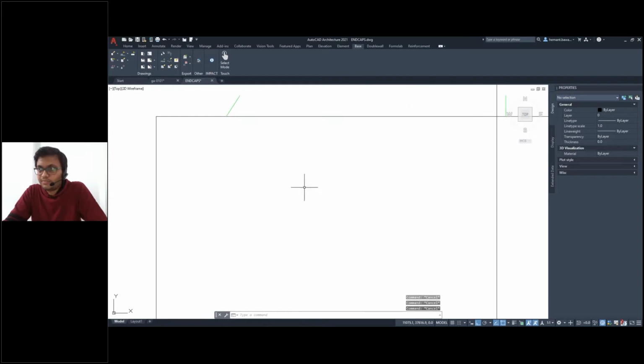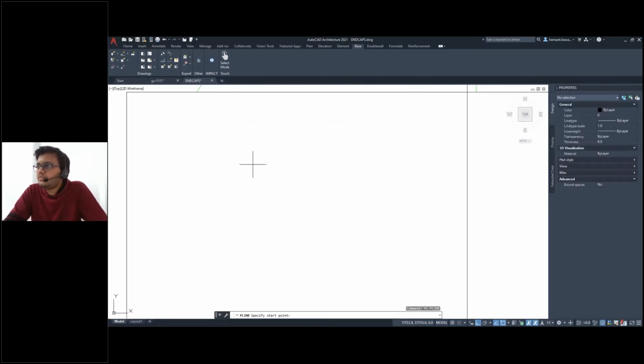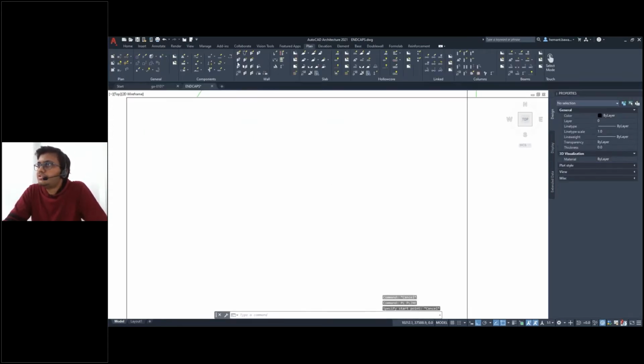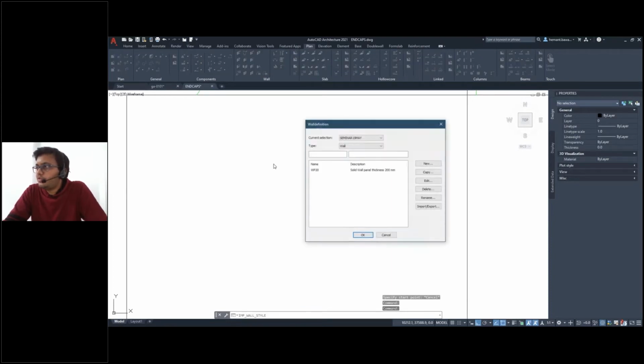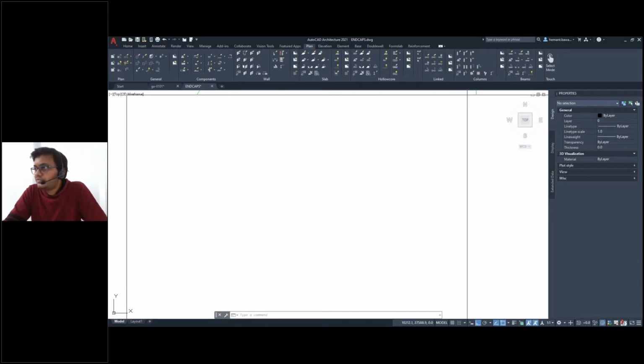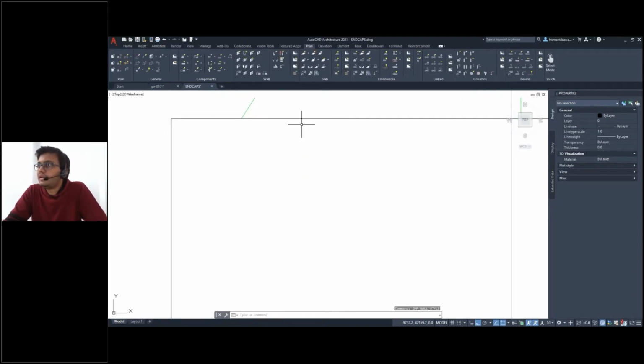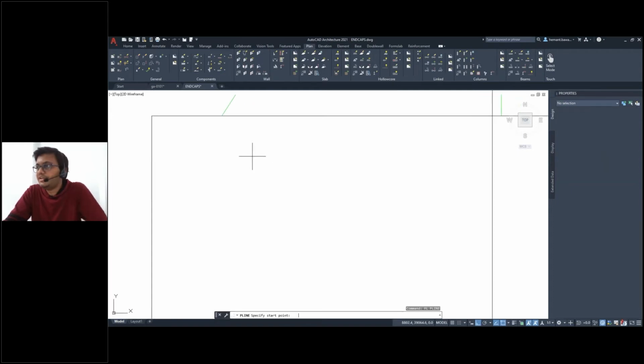So we'll create some of the geometry here. Before starting, we can check our definitions. For the wall I have the thickness 200 mm, and for the sandwich and insulation I have 270 and 340. So we'll start with the solid wall, and I will just start creating a geometry.